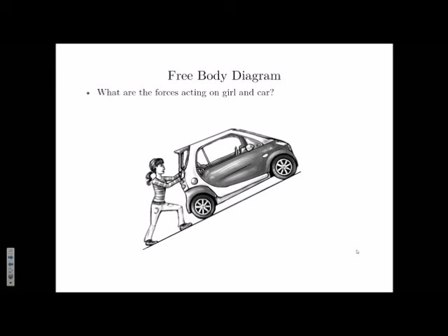And that's why, when you drive your car in snow or in conditions when things are kind of slick on the road, then you prefer to have an all-wheel drive. Why? Because all the four wheels can have traction or the friction from the ground. So in that case, if somebody tells you we have an all-wheel drive, by all means show the friction forces on all the wheels. But if, let's say, none of them are being driven, like in this case, if nothing is being driven, you can say, hey, I'm going to neglect the friction force on the wheels from the ground.